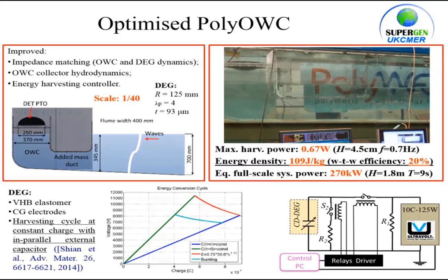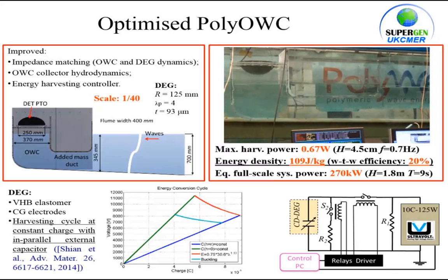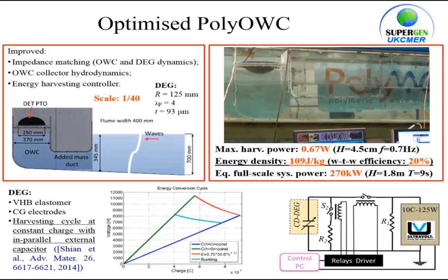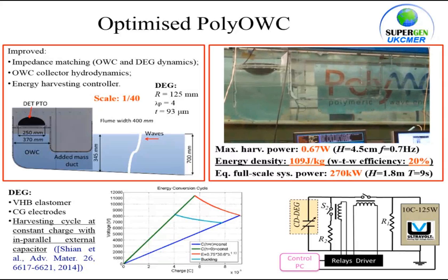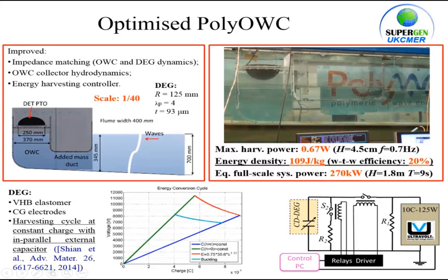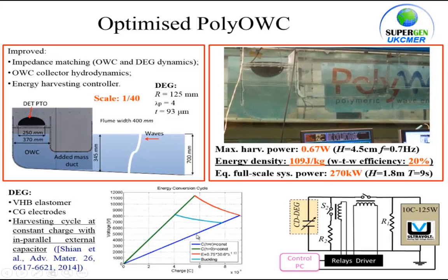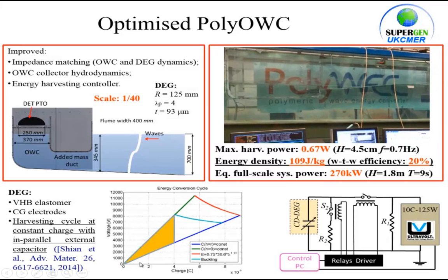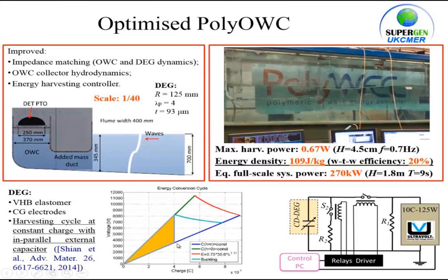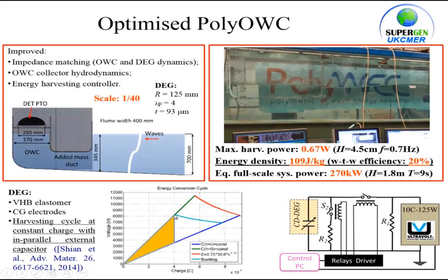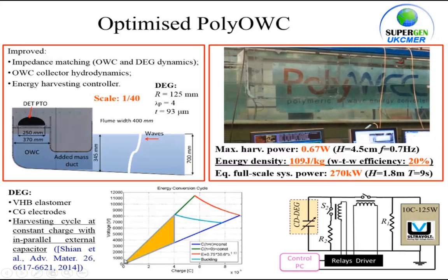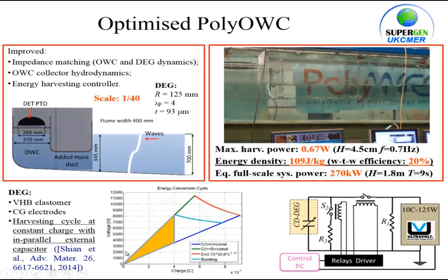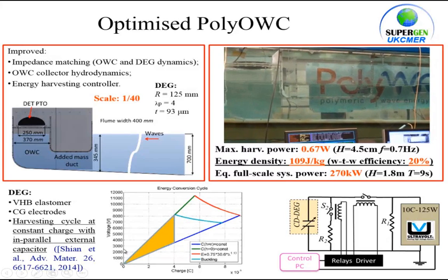A straight line on the graph represents a constant capacitance, which is basically a variable capacitor. So when you charge, you go up this line, then that's it fully charged, then you let it relax, and it comes back down this line. And that area there is the energy you get out.